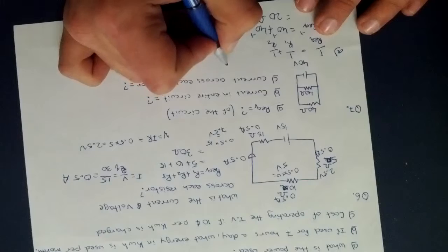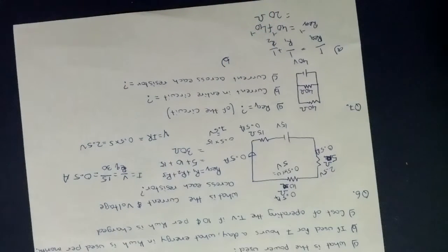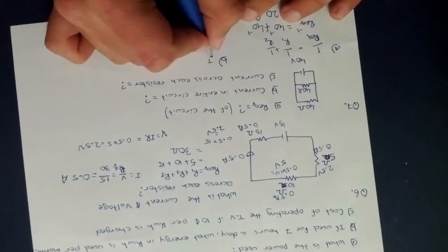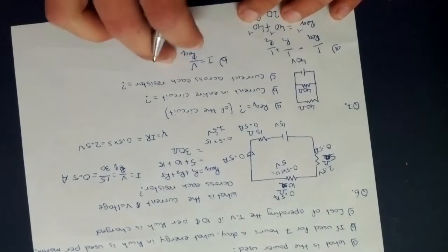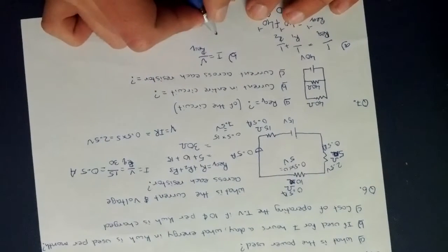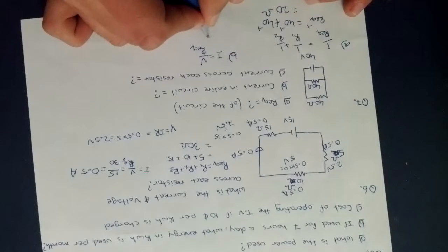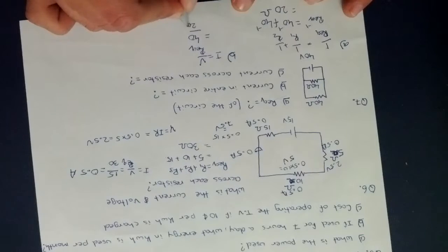Now part B. They're splitting it up into steps, but really we would do this anyway because this is what you have to do for every single thing. It should just come as second nature to you. So I equals V over Req. You should have this formula memorized because it's really important for circuits. We don't know I, but we know V is 40 volts and Req is 20. 40 divided by 20 is 2 amps.